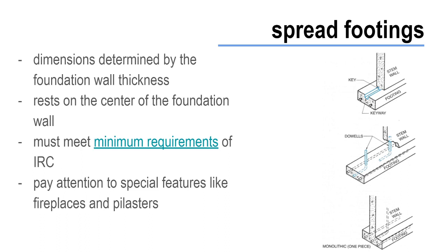The footings under those areas will be wider and perhaps even deeper than in just your typical areas of your foundation wall. And there may be times when even your footing or your foundation wall may be crossed or penetrated by a utility line, and so care has to be taken when you are penetrating a footing or a foundation wall. If there's not anything shown in the drawings about how that's going to be going through,